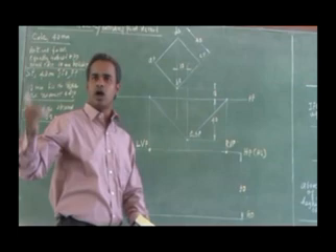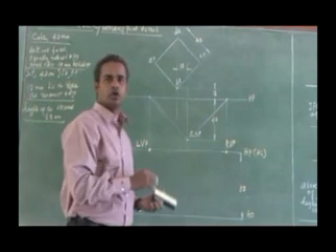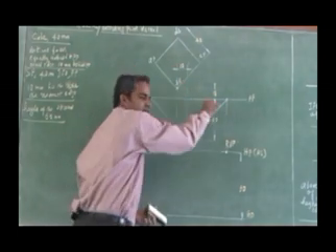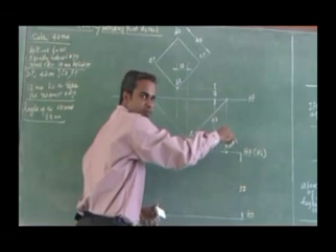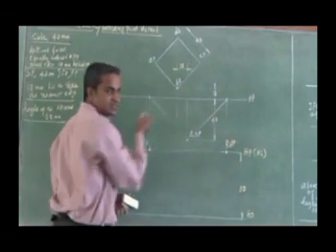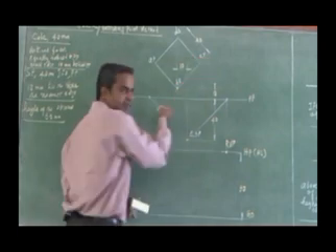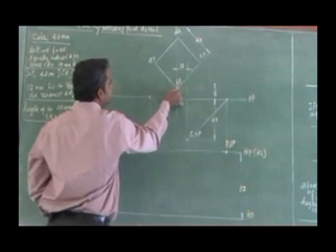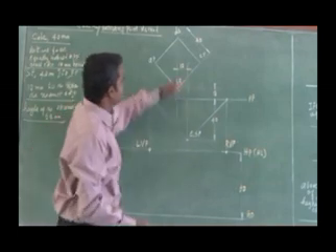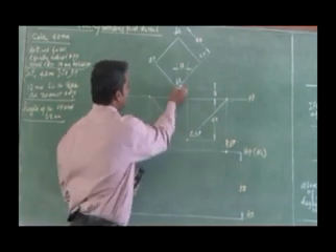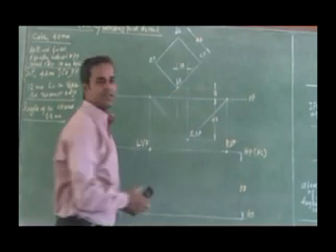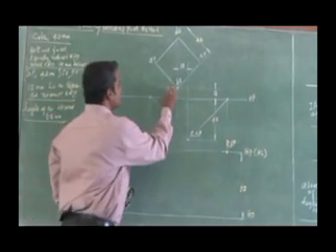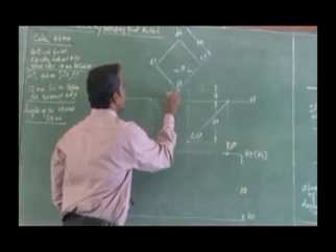So to draw the true height of the cube, I will extend this BQ corner this way, parallel to the left vanishing line or parallel to this face. Either I can extend like this or like this, it's up to you. I am going to extend in this manner, parallel to the right vanishing point. Is it clear? Now this B2, I am getting at an arbitrary location. It meets here, that is my location, say B2, Q2.